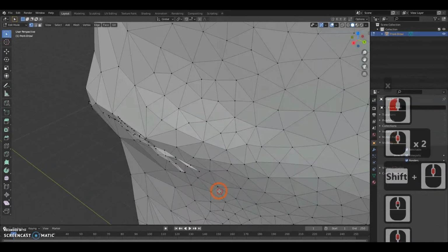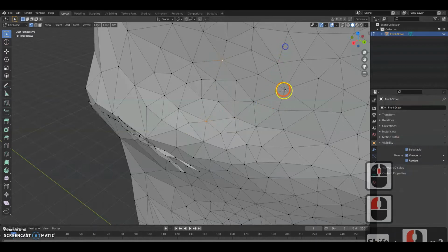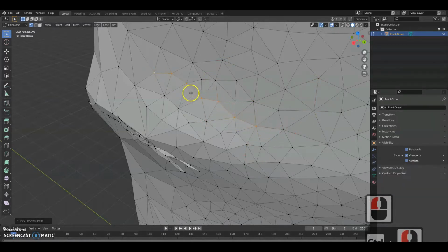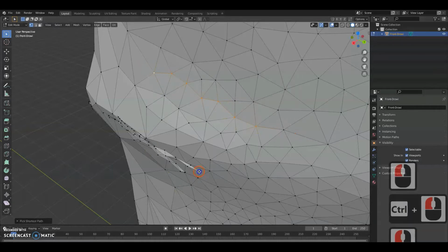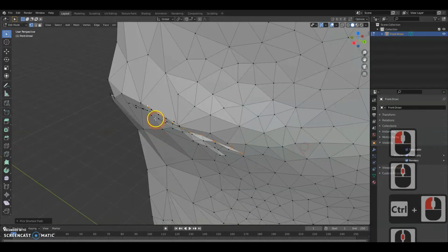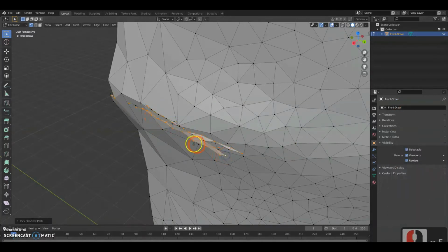And one other thing here is you can see if you grab a vertice and shift click any other vertices, it'll select all these different ones. However, if you grab one and control click farther away, it'll grab everything in between those vertices. So that's nice. So what I'm going to do is grab this and control click this issue, and I'll shift control click, so for everything here, all of this. This will just make it easier for cleaning up and everything.